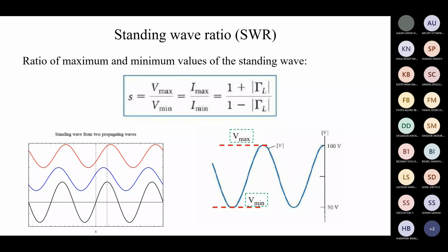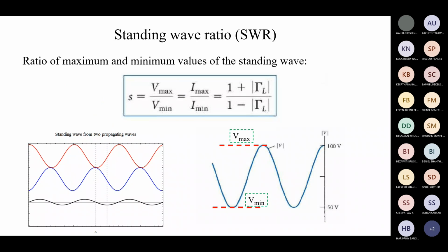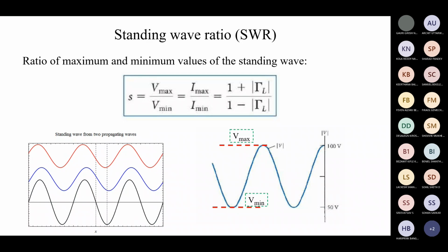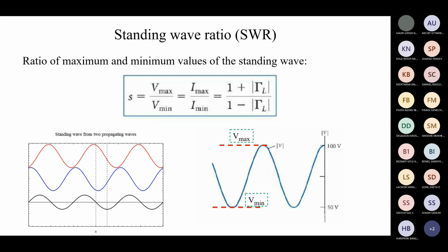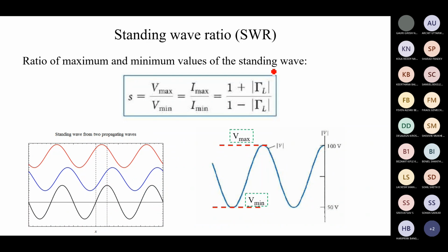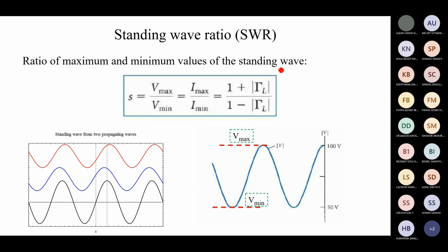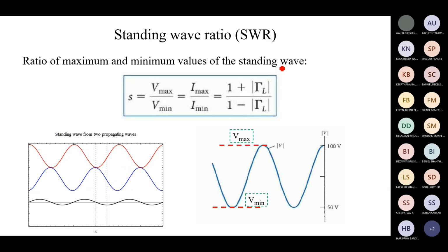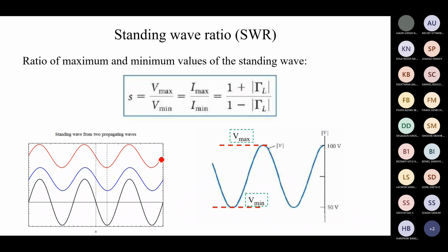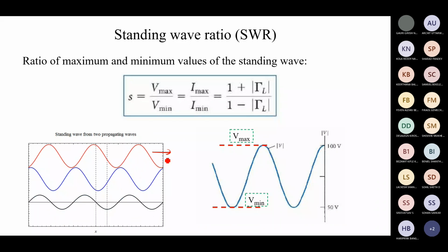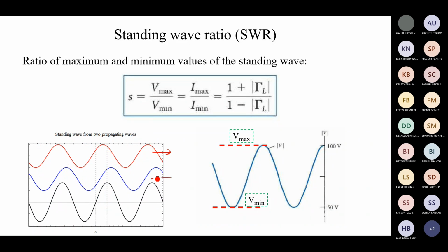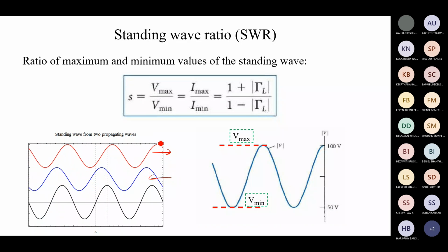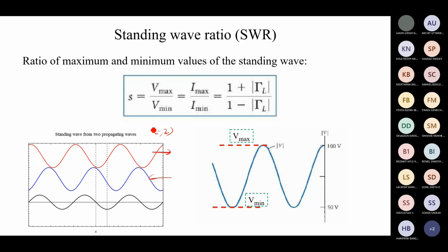But there are some other influencing factors available, so the same concept of reflection or the reflection coefficient can be described by other means. That is described by the traveling waves, the forward wave and the reverse wave. Both will add to each other at a given time and position.